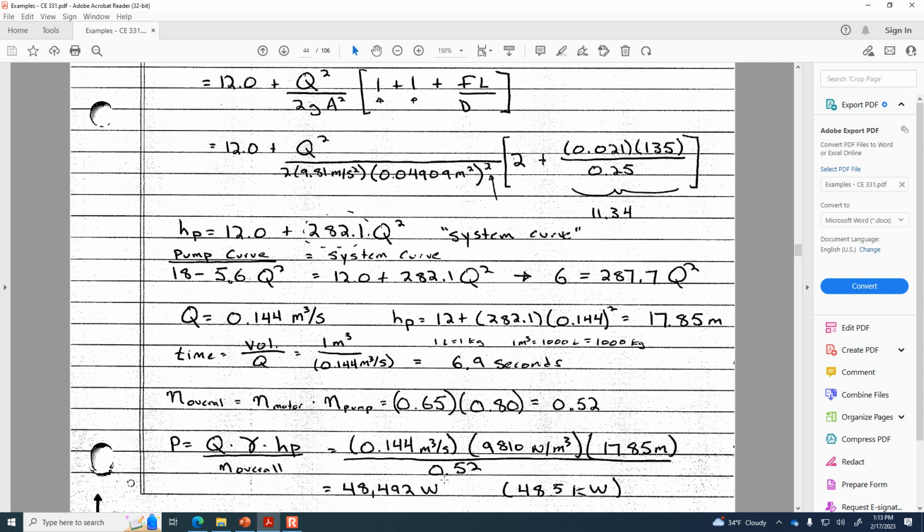It's usually between 5 and 10 kilowatts that you might be using. So here what we're saying is you're using between 5 and 10 times the average house just to operate this pump, which is a lot, but keep in mind that you're lifting 144 liters per second. You know how heavy a 2 liter of soda is.